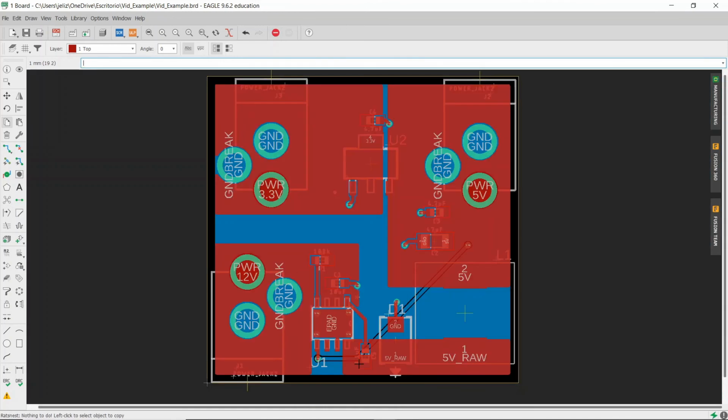Often you will want to mount your PCB to some other structure using screws or standoffs. This is where mounting holes come in. Using the hole tool, you can place holes and specify the hole diameter. Make sure not to have any traces routed near the vicinity of mounting holes. Screws can eventually wear through the solder mask, and you do not want screws shorting your signals. Shorting traces to the mounting chassis not only runs the risk of damaging components on the board, but can present a shock hazard.